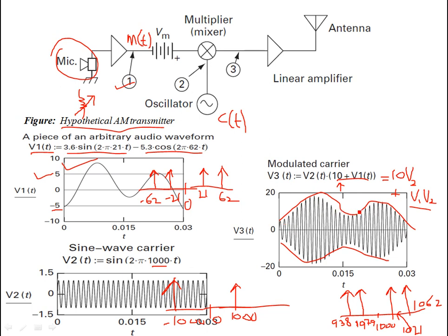That is how you are modulating the amplitude of the carrier, and you're not varying the frequency. The frequency remains intact. The zero crossings are the same, so the frequency stays constant. So that's how you shift the spectrum to 1000 and minus 1000.